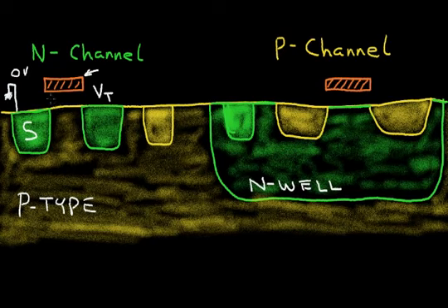And that's the critical voltage at which the strength of this electric field under the gate is just enough to start inverting this P-type region to an N-type region, and thus getting conduction between the source and the drain shown here. Now, as we increase the voltage at the gate, this electric field becomes more intense, and we drive this channel region down further.